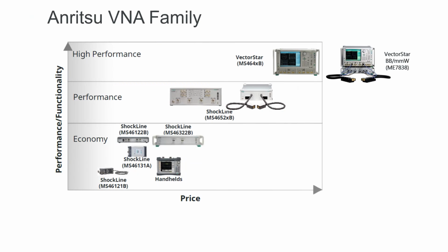Okay, continuing on with the VNA, which is really the measurement engine behind the measurements that Brian was talking about that are required to build up the model for the probe. We need a differential VNA. Of course, for the first 2 steps, it's an open and a short. That's a 2-port measurement. But we need the 4-port, obviously, to make the in situ measurement. And then later on, when we're using the probe and de-embedding it, we're talking about differential measurements. So once again, we need a 4-port.